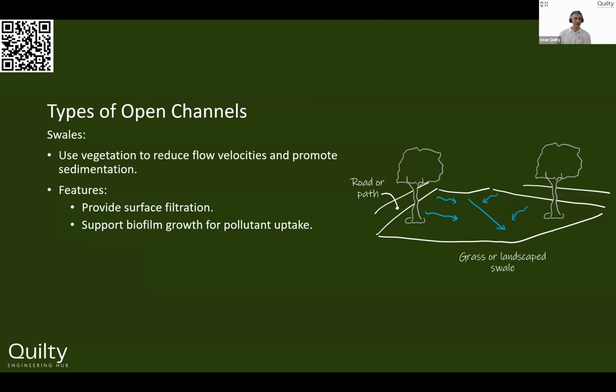And then, as a lot of you will be aware, using Ocean Protect philosophies, looking at stormwater quality, we can turn these swales into bio-retention type devices, where we have media underneath to allow the stormwater to soak through and filter through certain media as well. So that's swales. Essentially, it's just an open drain, but you're using vegetation as a bit of an engineering solution there.